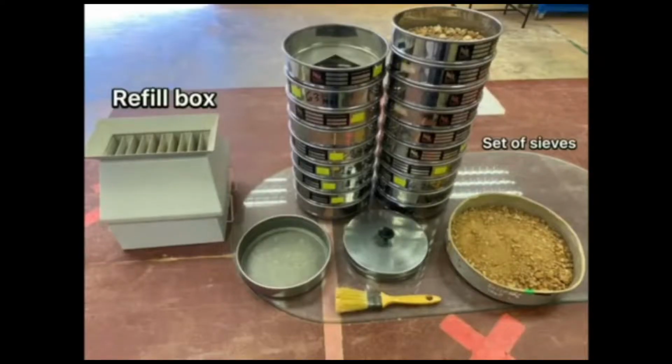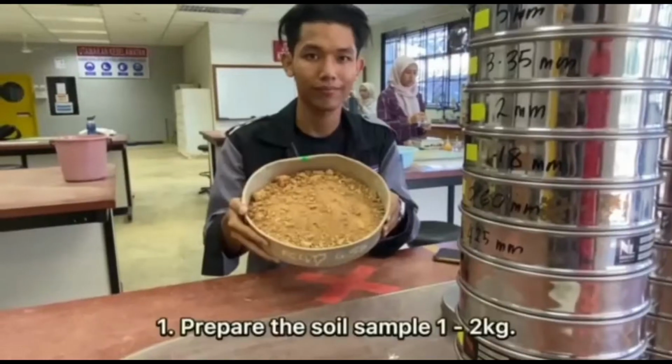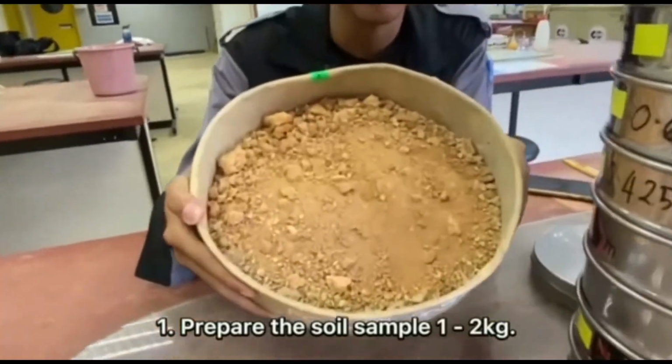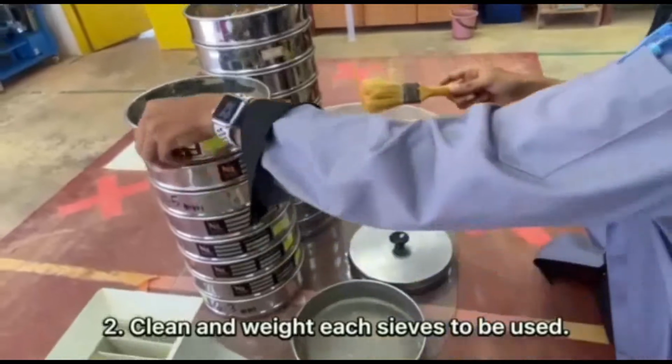The apparatus for the experiment is refill box, lid and receiver, brush, set of sieve and soil specimen, balance weight, and the last one is mechanical shaker. The procedure for this experiment is, first we need to prepare the soil sample 1 until 2 kg, and then we need to clean and weigh each sieve to be used in this experiment.